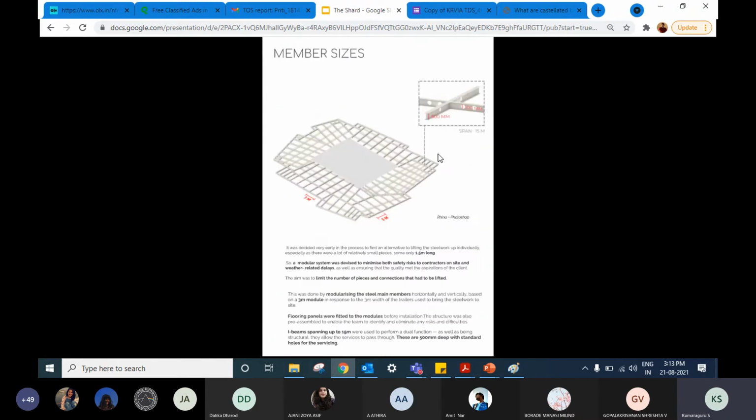It's a 500 mm deep beam. Well, 500? 300 mm. Okay. I just wanted to make one more clarification here. See, 500 mm, up to 600 mm, it's readily available in most countries. So they don't have to actually go for a castellated beam. So castellated beam is something